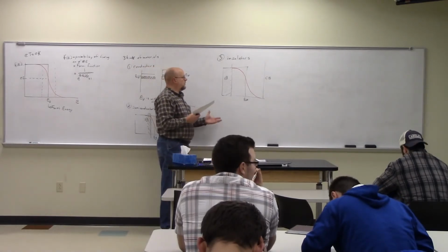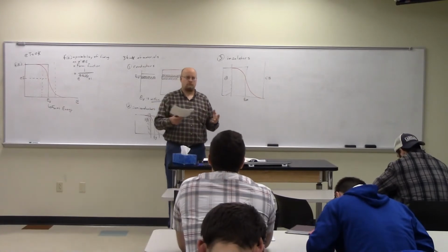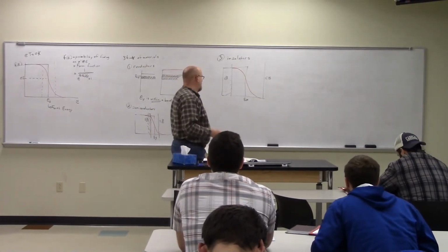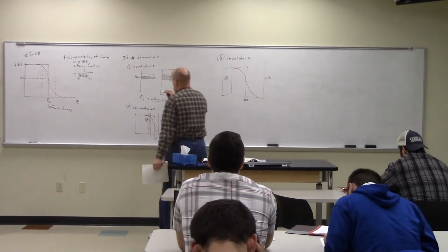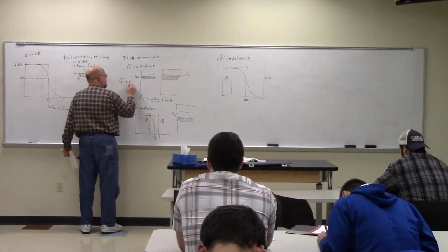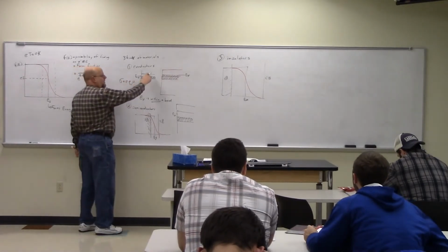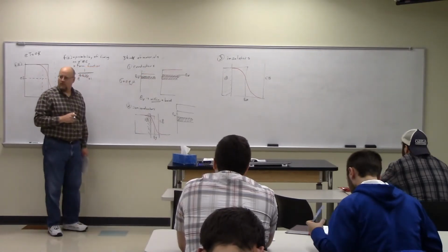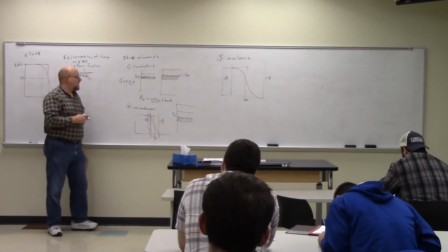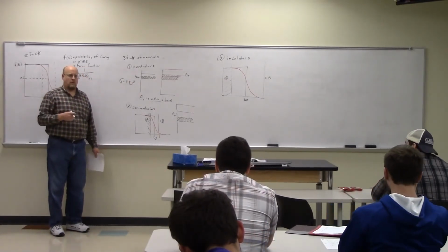Okay. So conductors, everybody cool with band structures? So conductors are defined by the conductivity, sigma, which is n, q, mu. So n we've kind of accounted for here with the Fermi function: how many we have available to conduct. q is defined by the essence of the charge carrier.